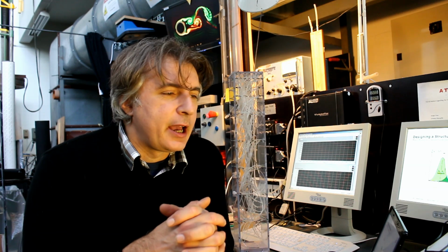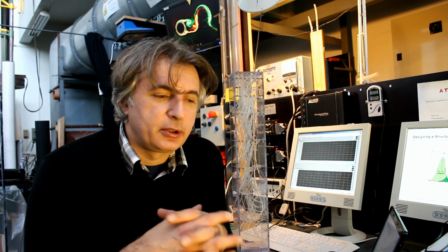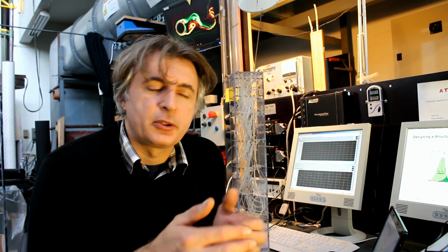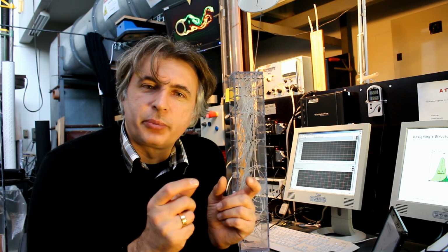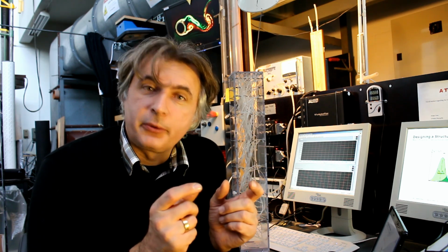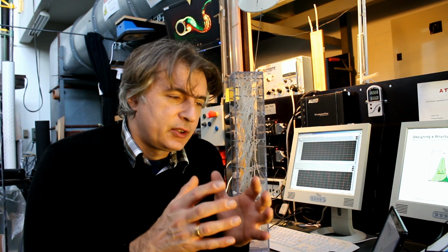So these are two stochastic variables, and both, even the material, are stochastically distributed, which means if you measure the elasticity modulus of one element, you get slightly a different number in the next test, and so on and so forth. So both are probabilistic variables, so to say.